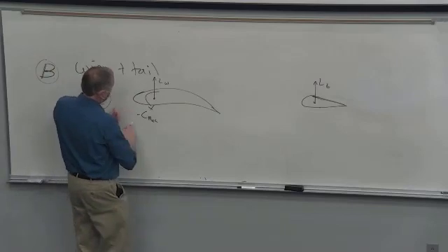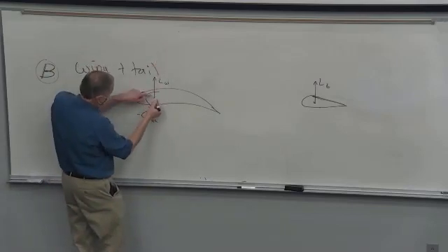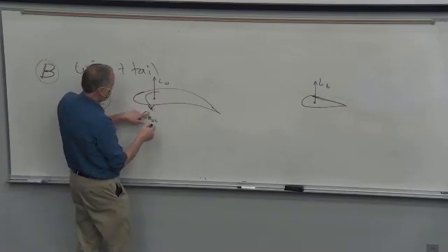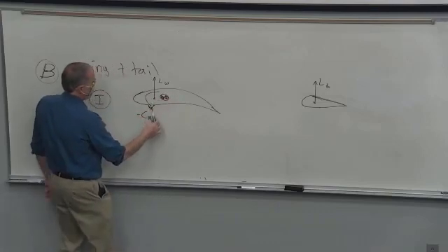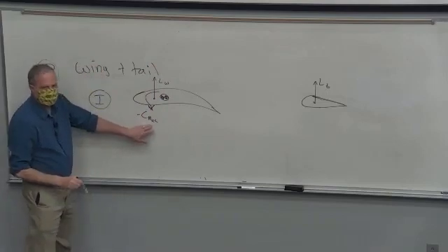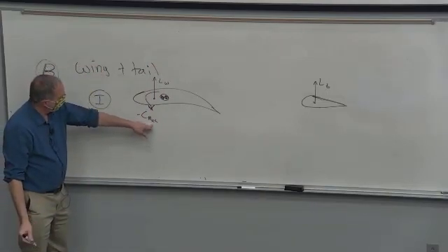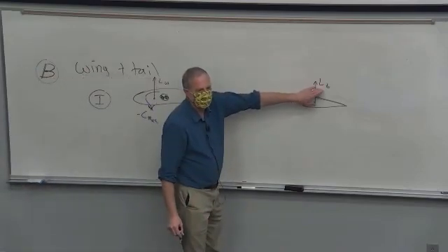So looking at this, the lift of the wing is going to be that way, and we get a CMAC. So we get a nose down couple from the lift distribution. So if we put the CG here at just the right spot, the nose up of the lift can cancel out the nose down due to this pure couple. Okay, so that's good. And so the lift of the tail can be pretty small.